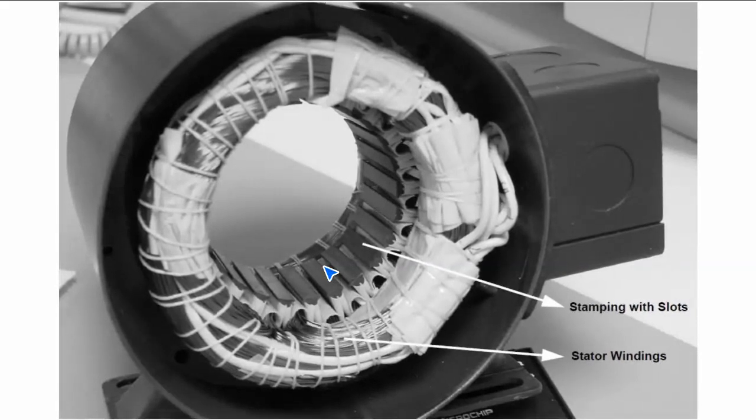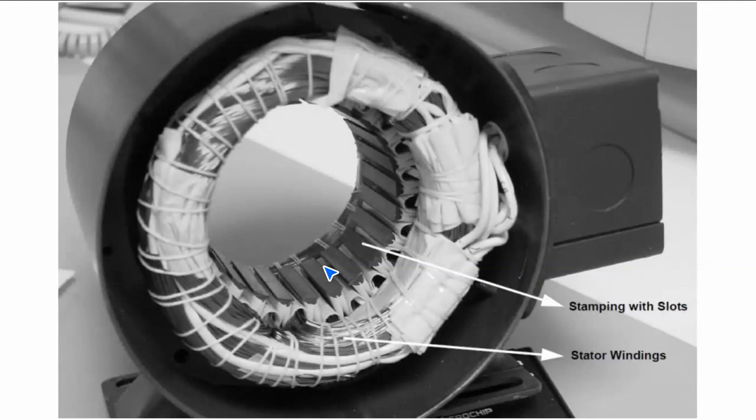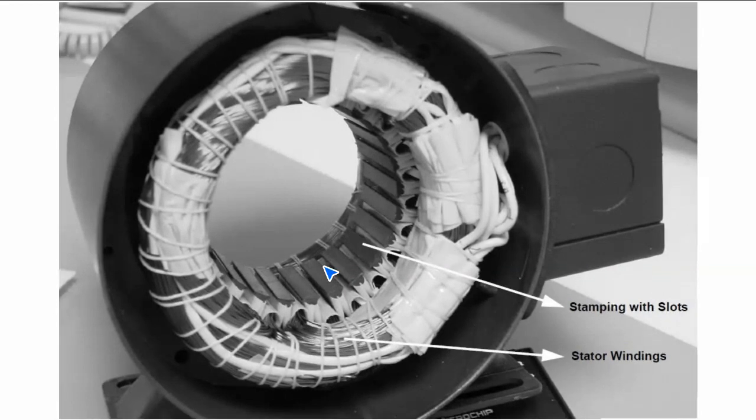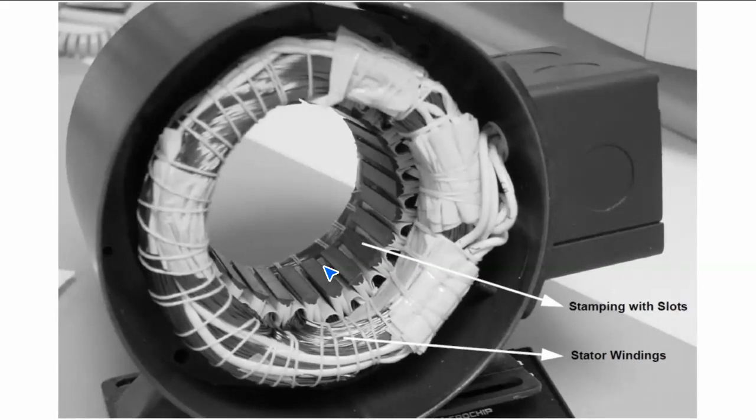Delta, you can remember from your conversion course, is a different winding type. The only difference is in the stator winding type. For example, generally we can use Y, but the main reason for delta connection in the BLDC is if you want to reach high speed, you can use delta connection. It regulates the current level of the motor actually.